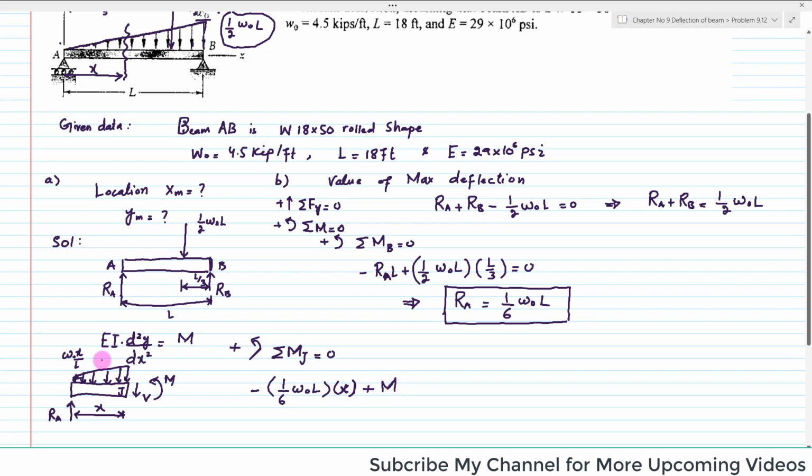Now due to this load W naught into X over L, if we convert it into a concentrated load, again this is a triangular load, so it will be equal to W naught into X over L, and it will act at X over 3, because here the distance is X, whereas above you have L, so it was at L by 3, here it will be acting at X by 3.